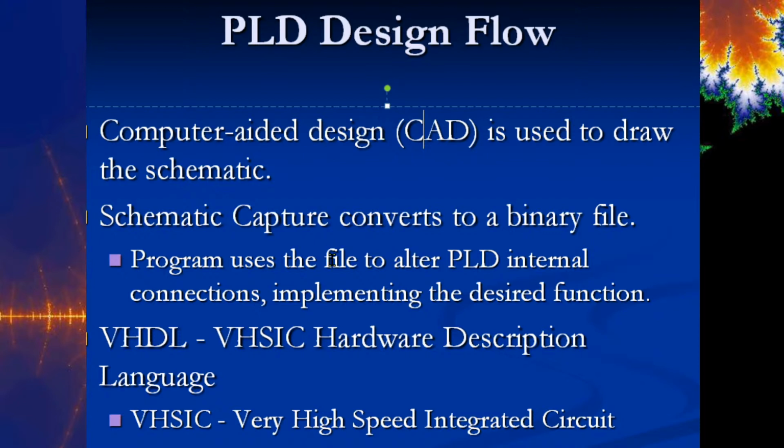So we are using the schematic capture. That's where we enter our gates, and we put in our inputs and outputs, and we make the required connections, and it'll show us where on the BDF file we have these attached address-wise in terms of the switches and the LEDs. Okay, it will also show us, like I said, the pin assignments.